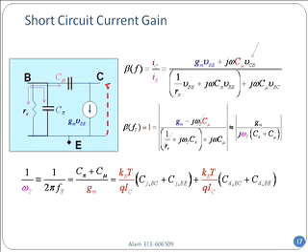Okay. The C pi and C mu, these are junction and diffusion capacitances. Do you remember the diode equivalent circuit, that there was a diffusion capacitance, there was a junction capacitance? Do you remember? So I have just split it up. Cj is the junction capacitance, Cg is the diffusion capacitance. I have two junctions, I have two capacitances. Done. Now, the collector side, I do not have any diffusion capacitance, right? Why not? Because this is reverse bias, heavily reverse bias. I do not have many minority carriers. So I will drop this term.